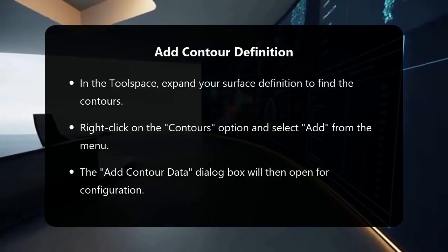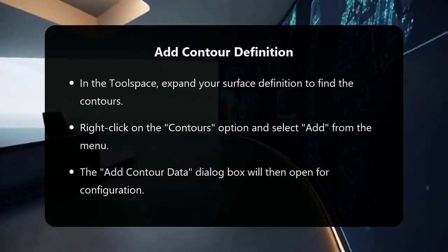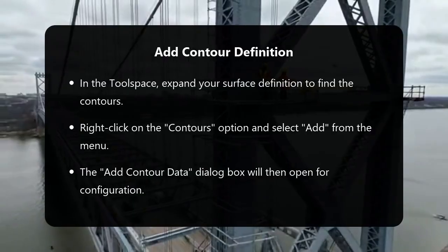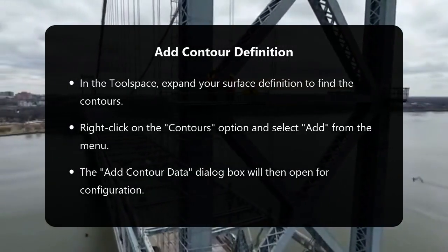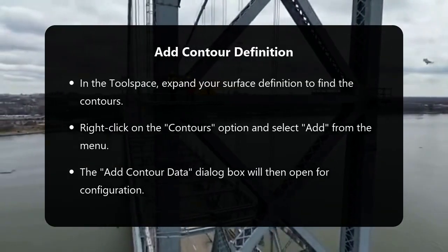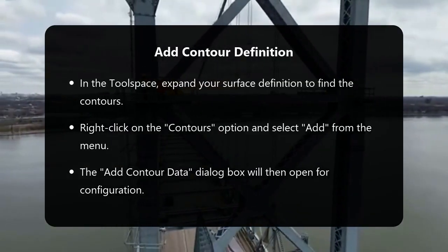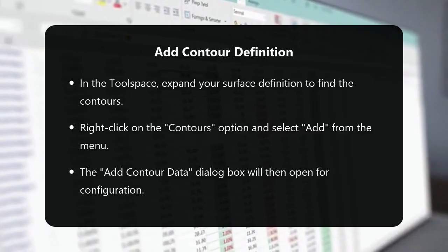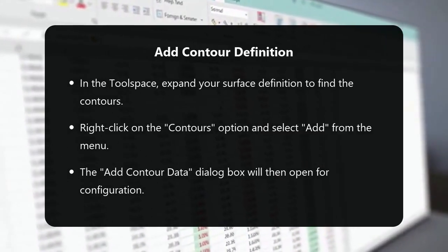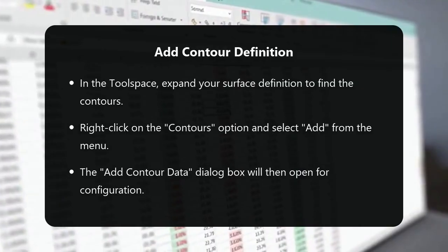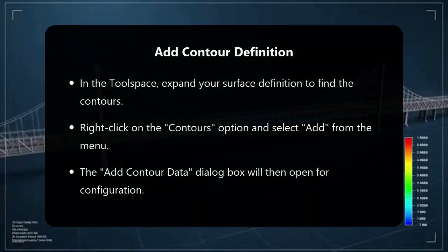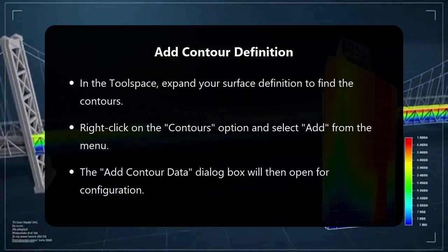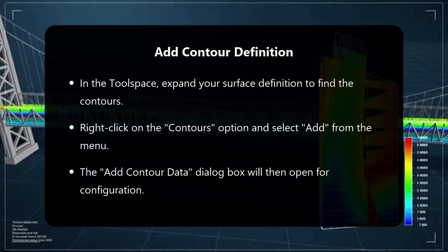In the dialog box, it is crucial to provide a clear description. Something like "e.g. contours from survey" helps you track where your surface data originated. Next, you will see options for weeding and supplementing data. Weeding simplifies the contour lines by removing vertices that are close together, which can optimize performance without significantly affecting accuracy. You can set weeding factors based on distance and angle. Supplementing factors do the opposite. They add vertices along straight segments of your polylines to ensure the resulting triangulation more closely follows the intended ground